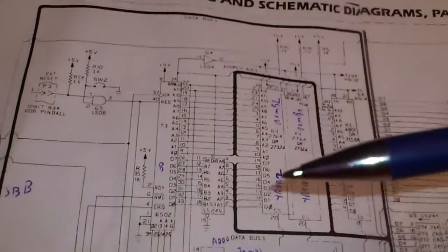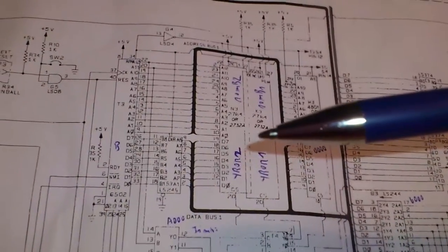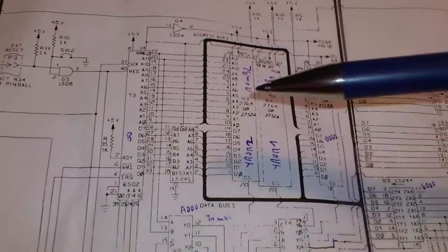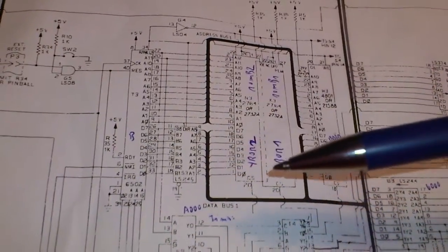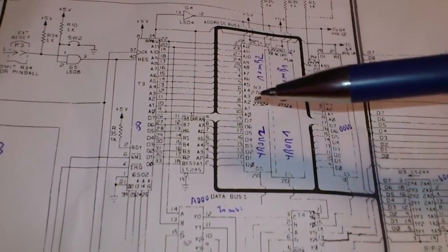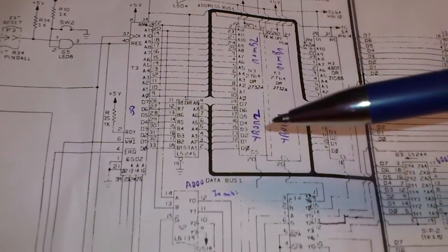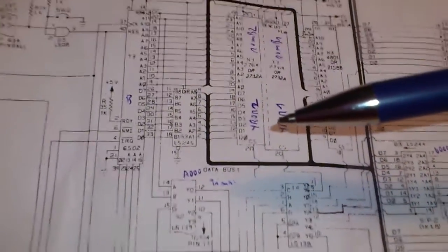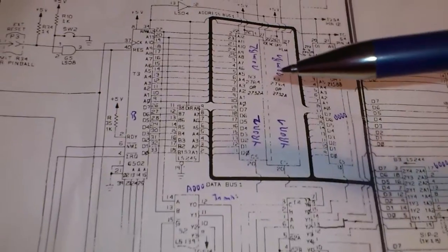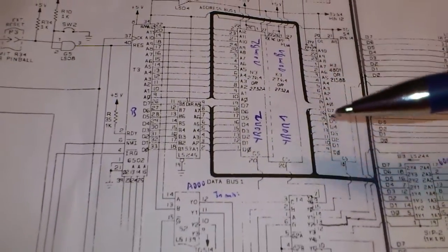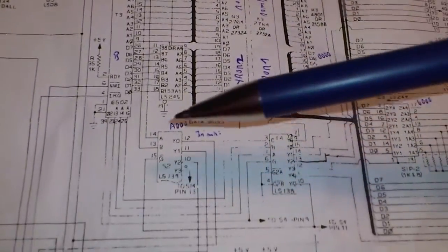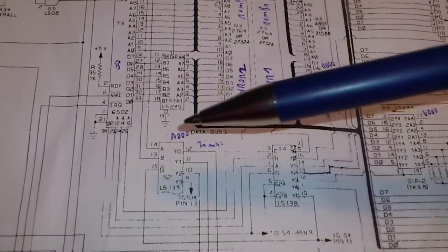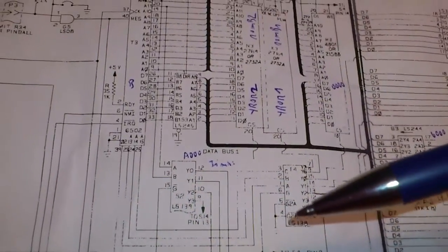If we take a look at the more sophisticated CPU, then we figure out that that one has 2 banks of 8 kilobytes, so in total 16 kilobytes of ROMs, because it has to run the programmable sound generator, so it's playing the tunes, as well as generating the speech. And it also has 1K of RAM on that side here, and a little bit more complex address decoder because there are more peripherals sitting on that one here.